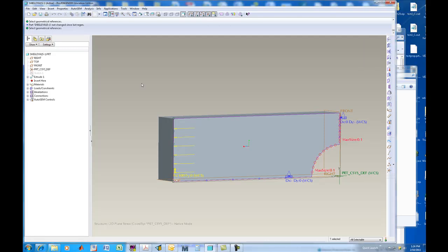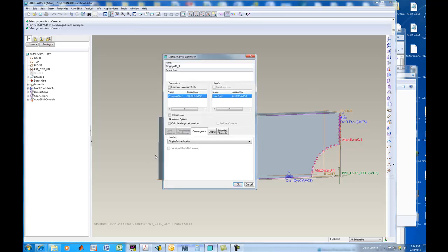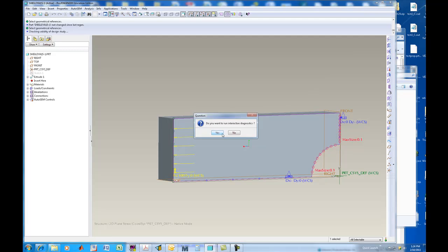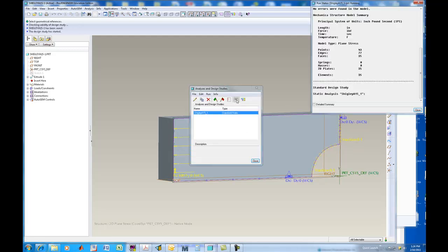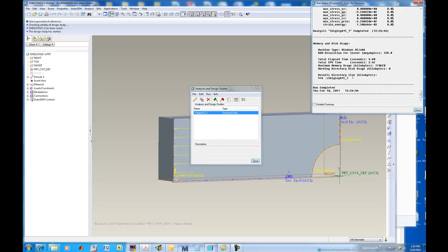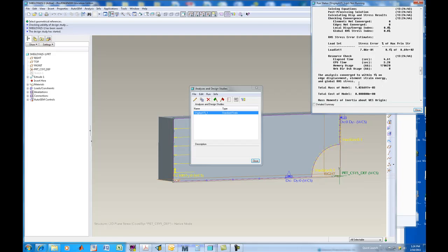Okay. And let's go back to now analysis. And let's go ahead and change this into a multipass adaptive. And let's aim for a 1%, which is not going to be reached. And maximum polynomial order. This is going to run fast. So yes, no. Let's watch it run. 3, 5, past 7. It's done. Did it converge or not? The analysis did converge to within 1%. Let's take a look at the results.